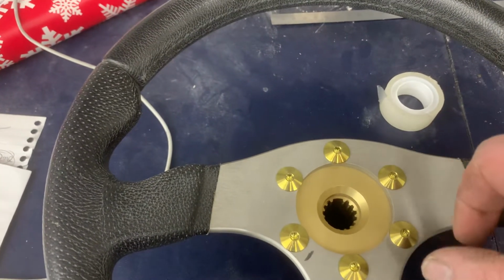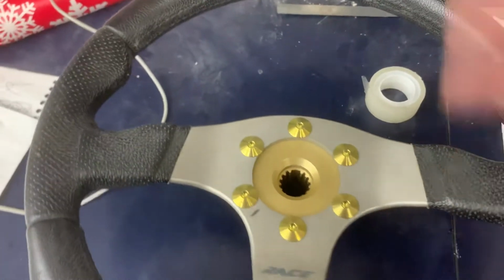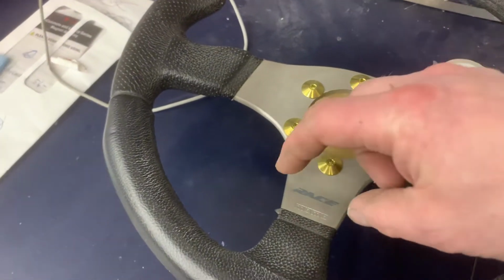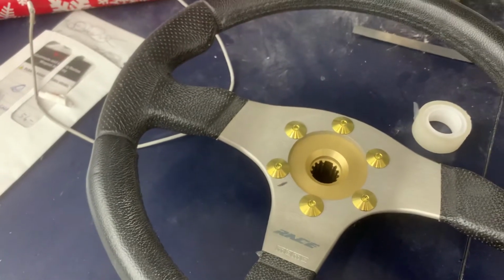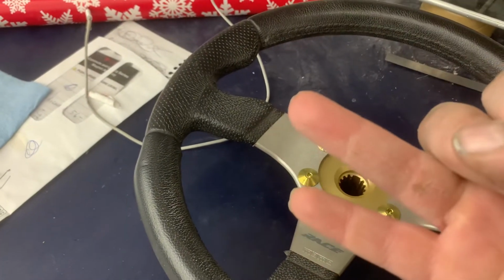You have a second rotary switch possibly for, say, the wiper delay, so that works on that. You can have the wipers on and off, fast and slow, maybe the indicators, all depends on what I want to put on there. But basically that little tiny module, I say it's CANBus, so it just has a CAN high, CAN low signal, and then 2 more cables that are the power and ground. So 4 cables will connect the steering wheel to the system.